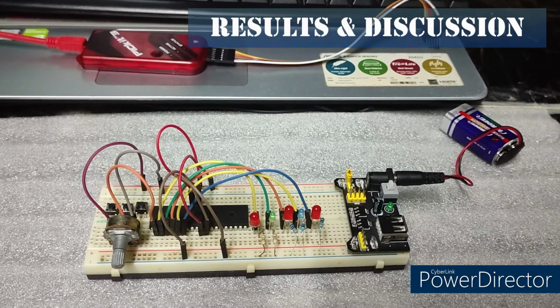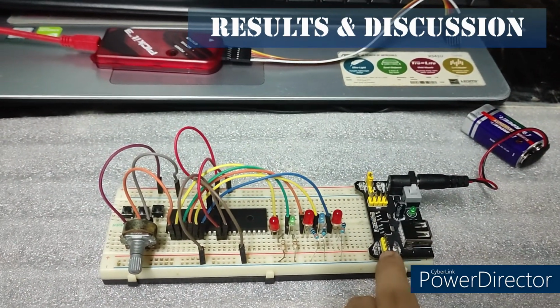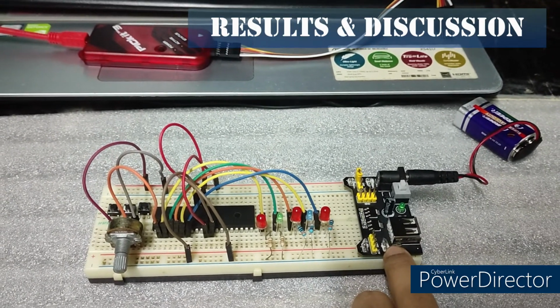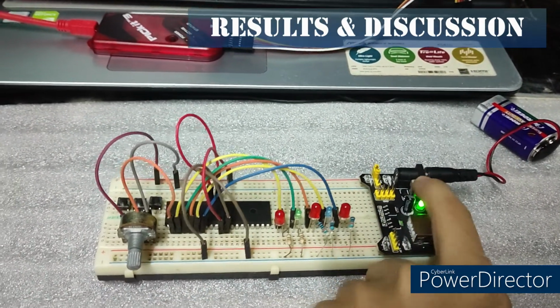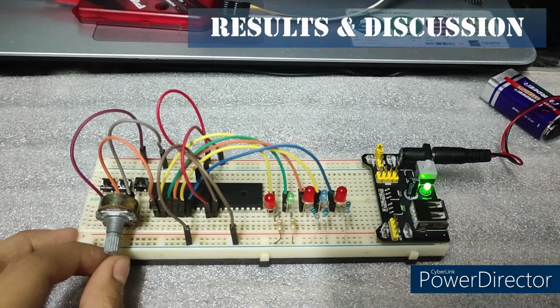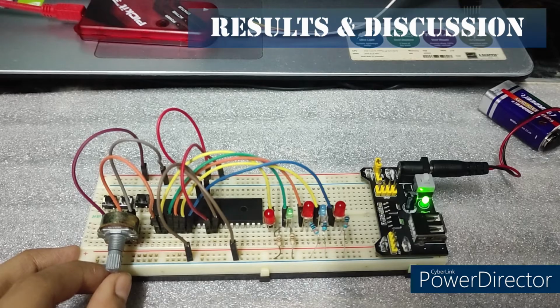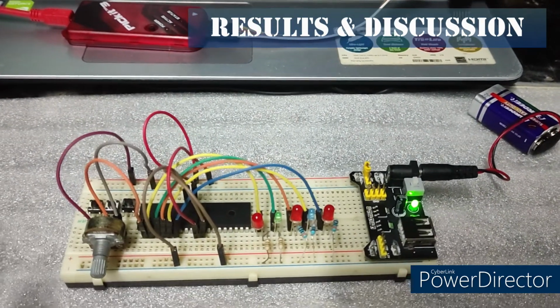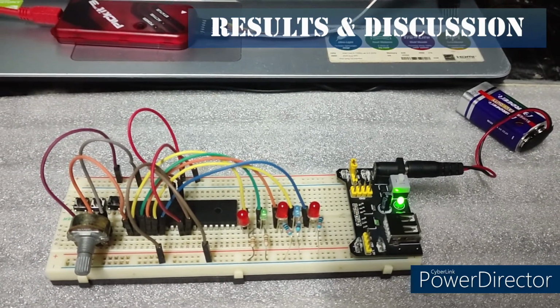Now, to test our circuit, we connected a 9 volts battery with our power module here to convert the 9 volts to 5 volts, or literally to step down the voltage to avoid damage to our IC. So now let's turn on our power module. Now we will be adjusting our potentiometer here, just like how we turn the control knob of our electric fan when we want to adjust the fan speed, to make the air cooler inside our room.